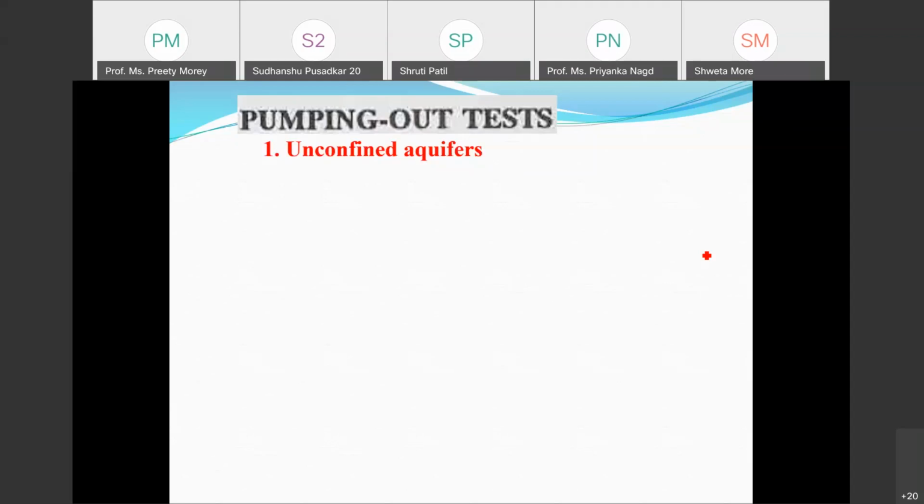When I am removing the water from this borewell, after a certain period of time, the water which has been removed will lower your water table, and that lowering will continue till it becomes constant. That means the soil has that much water continuously flowing through the borewell, but your water level remains constant. Using this technique you can find out the field permeability of the soil.